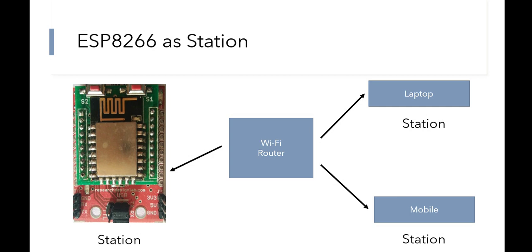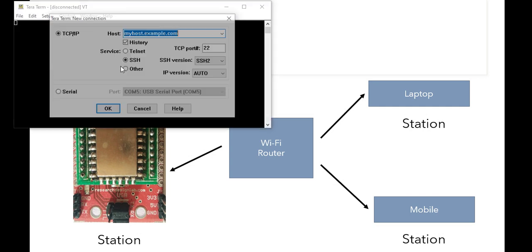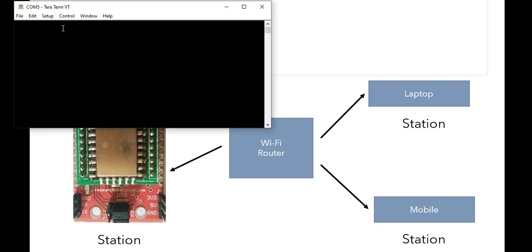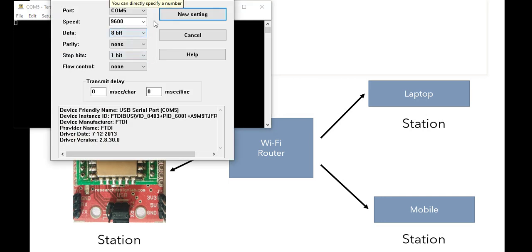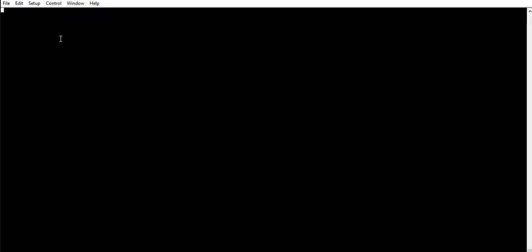So let us connect the ESP8266 board. So as usual this is connected over COM5, and 115200 is the default setting. Now in this scenario, if you want to set this up as an access point, initially import network, so that that particular module will be used here.